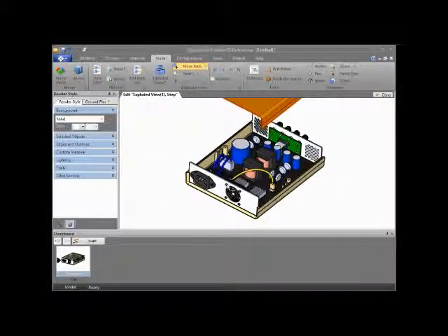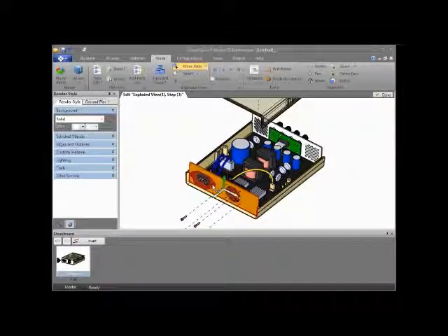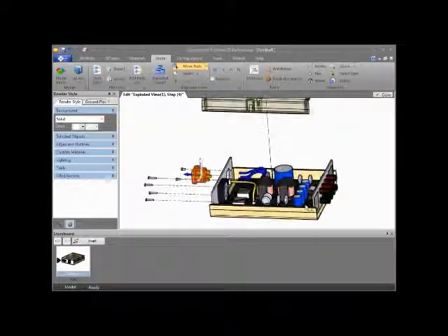And let's just go ahead and get through this. Now the explode tools for Quadraspace, we're only going to do some translations here, but you can also do rotations and scales. Scales can be used to compress springs, for example. Let's see here. So let me go through here piece by piece. We're just going to make a quick exploded view of this.